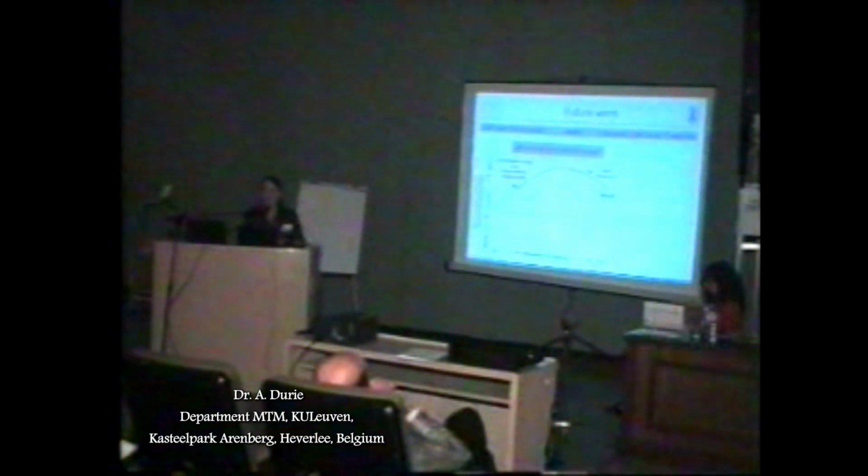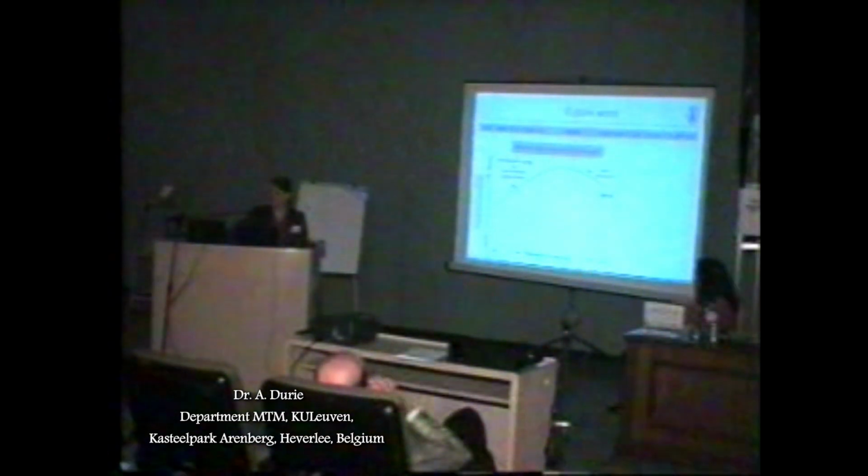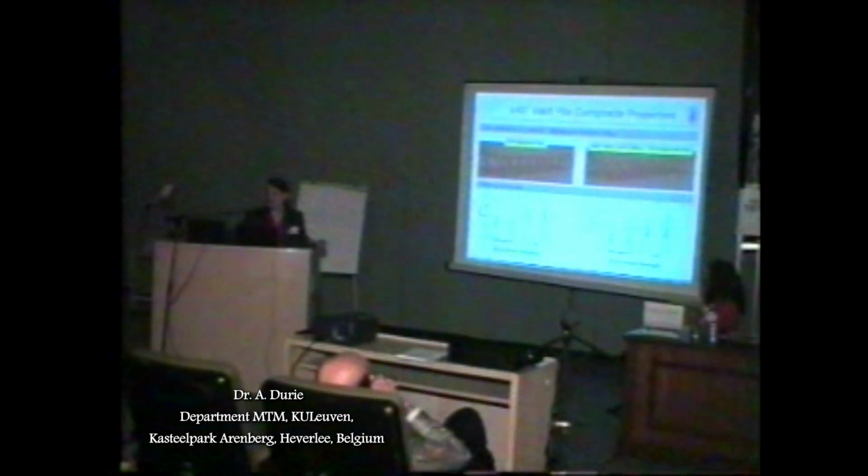For future work, if you have a look at the samples, you'll see that they're actually really initial work, the beginning of the work. So what we're expecting is that we'll maybe not necessarily need so much ±45 degree weft, because if you have a look at the results, the core shear strength, or the core shear modulus, is much, much higher in the weft than the warp, so we might not need to have so much ±45 crossing in it.